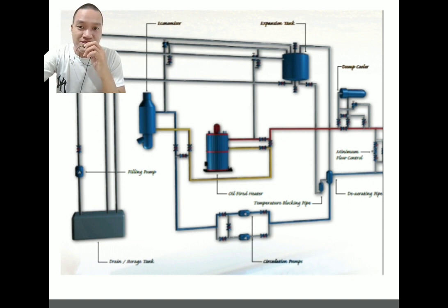Next I will discuss the working operation, the starting and stopping of the system. First is the starting procedure. First, you start your system pump to get the fluid flowing through the system. Second, after you know you have a good flow, you apply the heat.